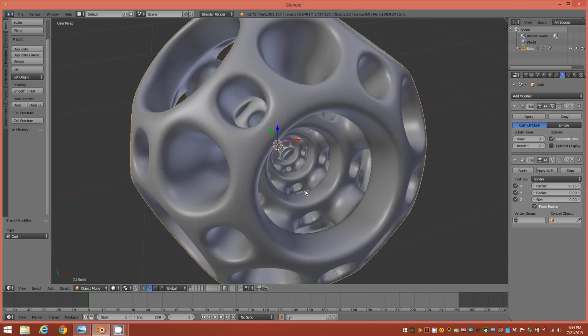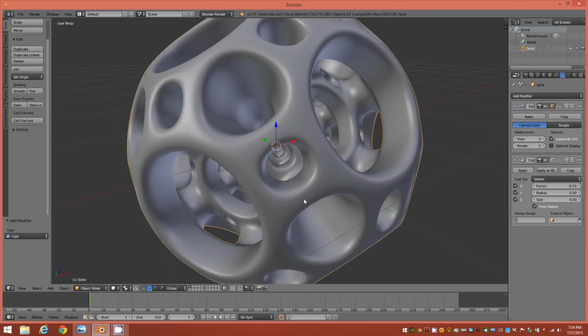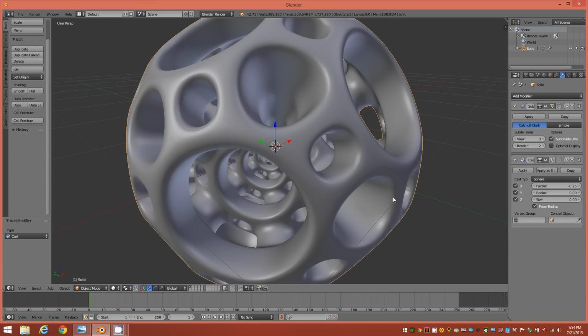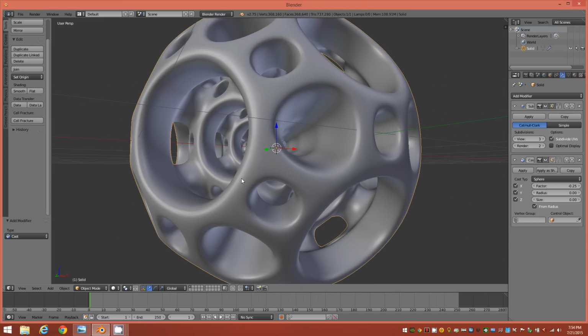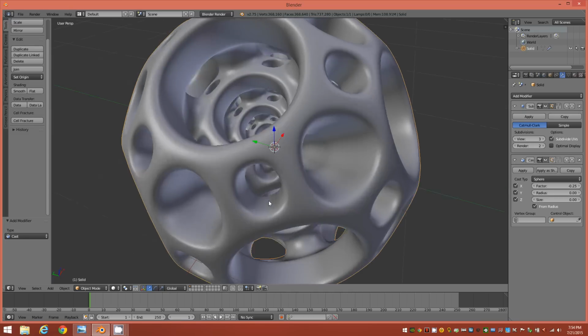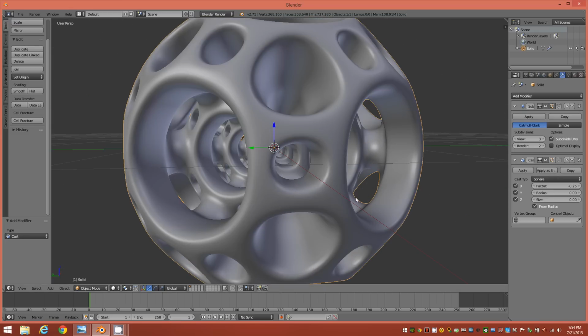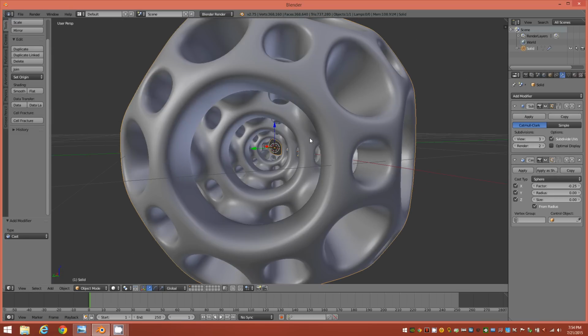That's about it. I think if you're going to 3D print this, it would be wise to hollow out the interior, because this would be an expensive print as is. So in order to do that, you just apply another shell modifier on top of this and adjust the thickness, which would give you interior walls inside here.